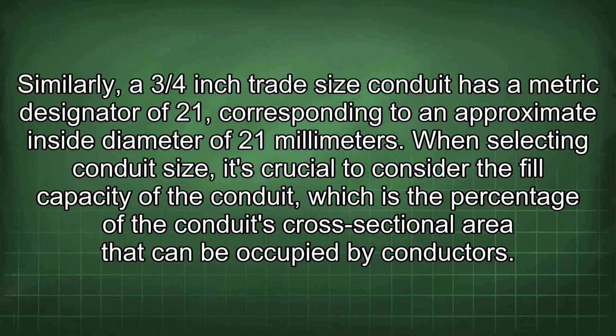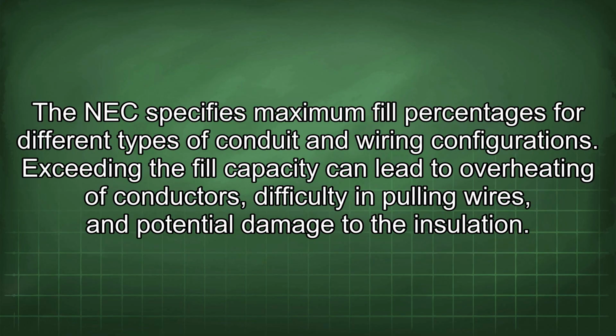When selecting conduit size, it's crucial to consider the fill capacity of the conduit, which is the percentage of the conduit's cross-sectional area that can be occupied by conductors. The NEC specifies maximum fill percentages for different types of conduit and wiring configurations. Exceeding the fill capacity can lead to overheating of conductors, difficulty in pulling wires, and potential damage to the insulation.